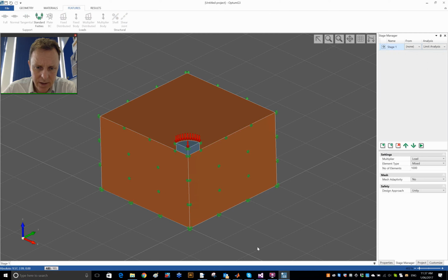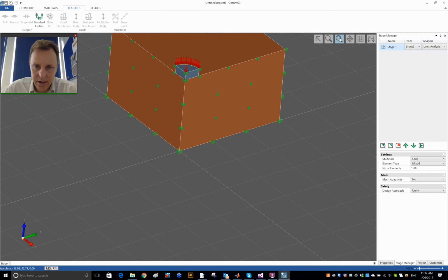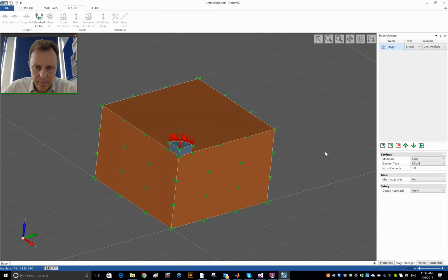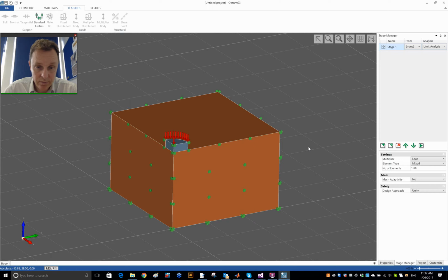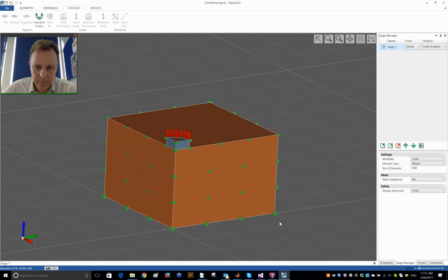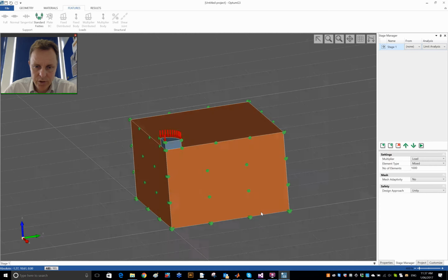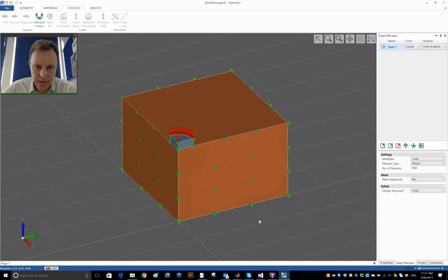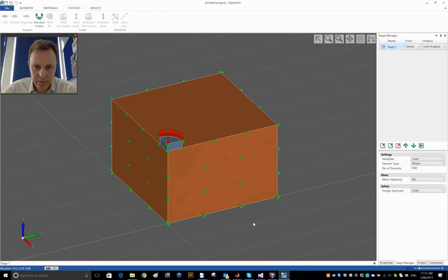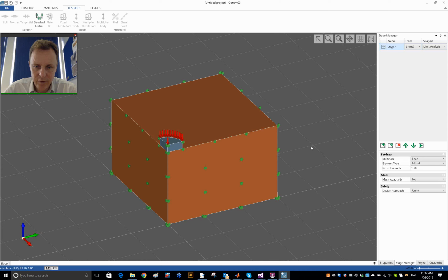I should say as well, I completely forgot that, but better late than never. 2 important keyboard shortcuts that you need to know are Control, moving the mouse rotates the solid, and Shift pans. Control and Shift really take care of everything you need.